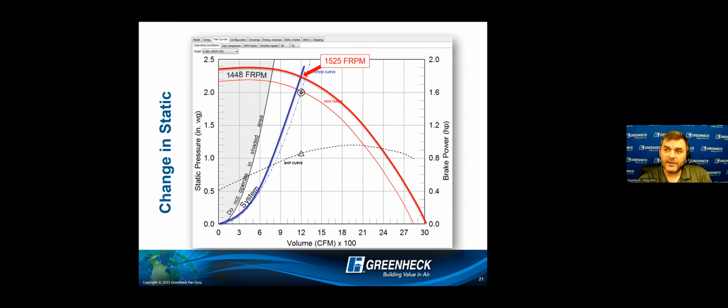There's more system resistance. There's more and faster moving air through that ductwork, so I'm going to hear it better. Now we have to balance. We have to move the right amounts of air. I'm just kind of cluing everybody in on the unintended consequences of this scenario happening to you. You may all of a sudden have enough sound change where people see it, hear it, and sometimes complain about it.